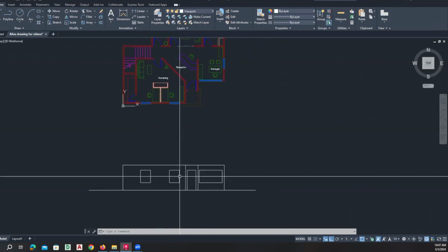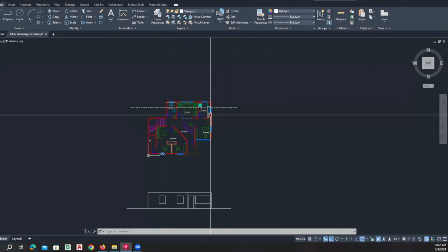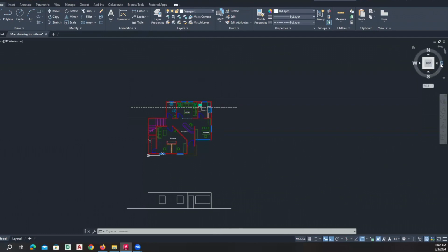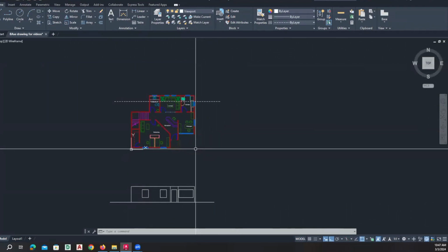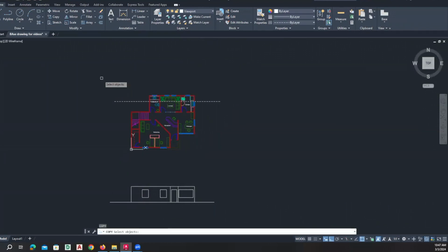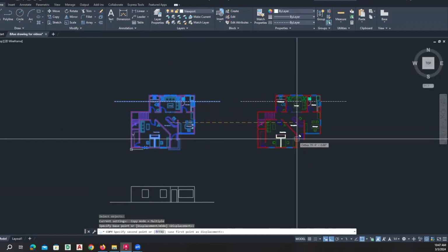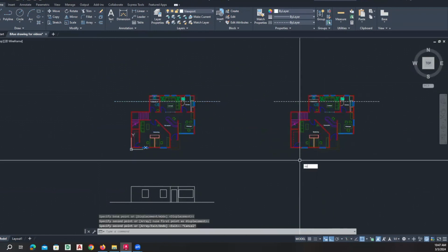And that's how you probably would have learned how to do projections. Now, the next part, which is that what if we wanted to draw the elevation that's on this side of the building, right? Looking at the view cube, that's the east side of the building, right? So if we wanted to draw the east side of the building, what you might have learned how to do is take your plan, select all of the objects in your plan, copy that over some distance, and you might have rotated this